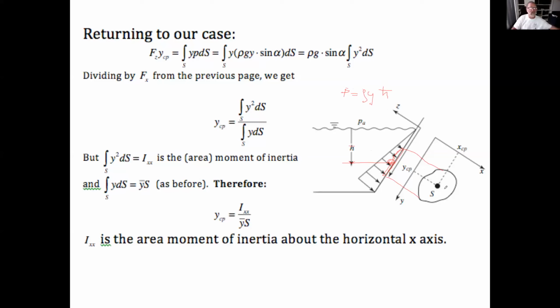And then the force is going to be equal to the pressure times the area of the surface. We did that before. So now we need to do the same exercise we did before, but we're assuming that the shape is not necessarily simple. So we need to actually do integration, which is dS is going to be this. This is the dS, we know dS. Okay, so remember Fz we already know, and Fx. So for Fx we have to have y, because we're moving around the coordinate.